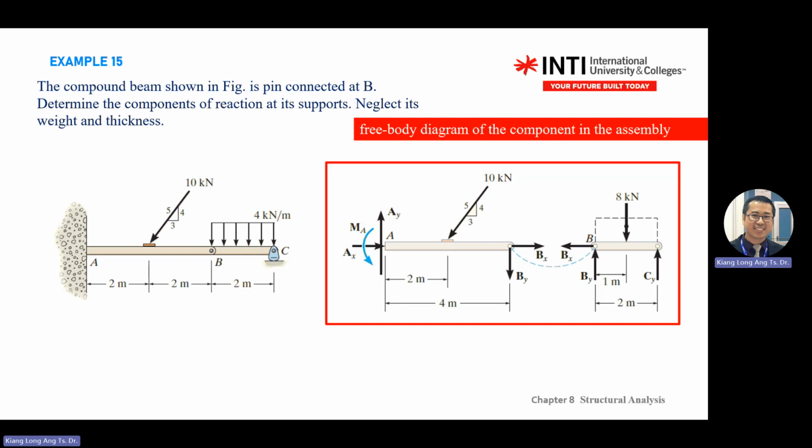But normally, we call it textbook common sense. If you dismantle the object, we always assume the two members tend to join together. So the arrows will always push like this. Even though we cut the member or we have a pin, we always assume that the two members want to join together. So start to practice this: BX and BY always pointing to each other. This is what we call common sense, the positive sense.